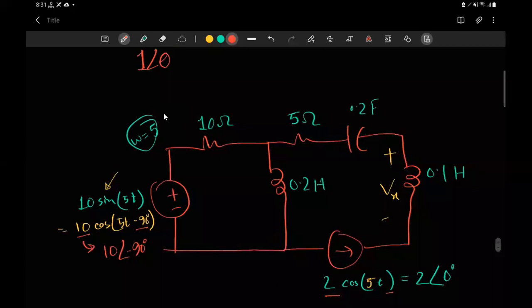Now let's look at the RLC elements: resistors, inductors, and capacitors. What's the impedance of this 10 ohm resistor? 10 angle 0. Yes, 10 angle 0 basically just means 10, so you could write it that way too, but for completeness I am going to write it as 10 angle 0. I'm giving it the name Z1. I think it will be easier if we give each a name. Okay, so let's call the next one Z2.